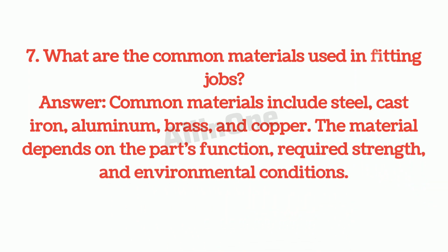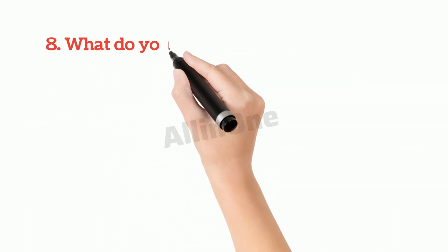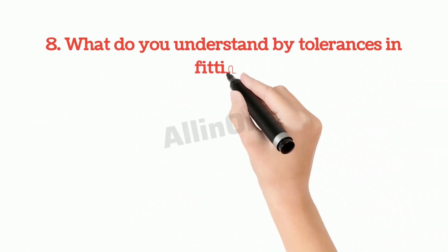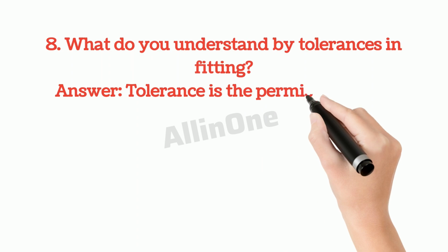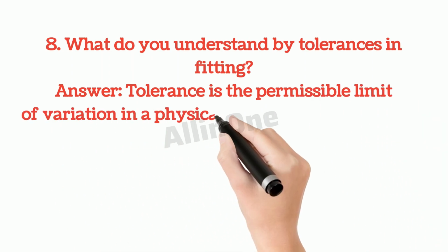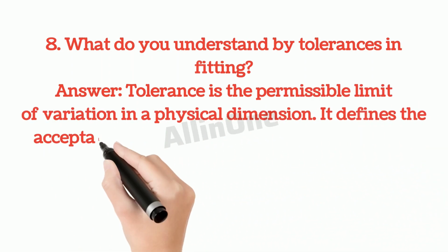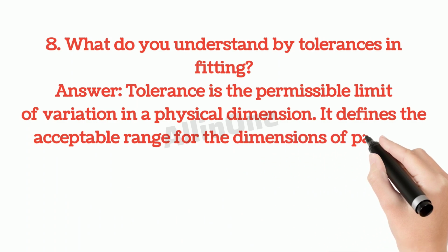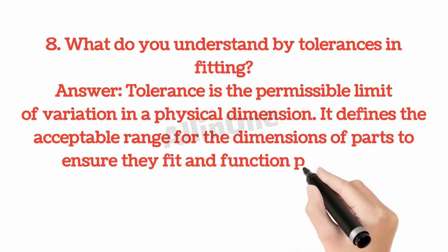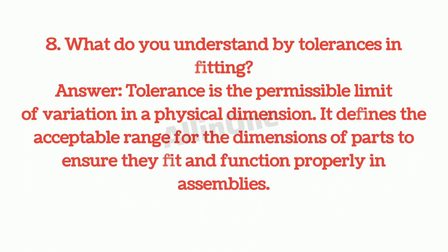8. What do you understand by tolerances in fitting? Answer: Tolerance is the permissible limit of variation in a physical dimension. It defines the acceptable range for the dimensions of parts to ensure they fit and function properly in assemblies.